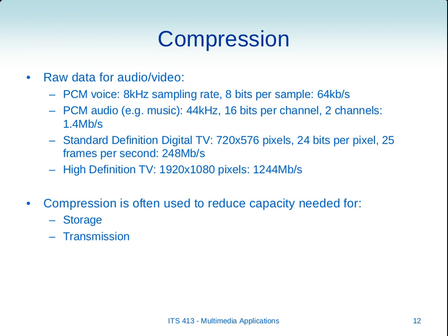There are some variations, but an example resolution of standard definition digital is 720 by 576 pixels. 720 across, 576 down. 24-bit colour and 25 frames per second. So we repeat the images 25 times per second, multiply them together, 720 times 576 times 24 times 25 frames per second is about 250 megabits per second.